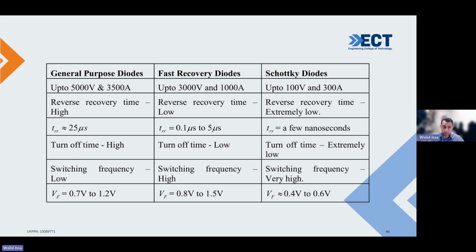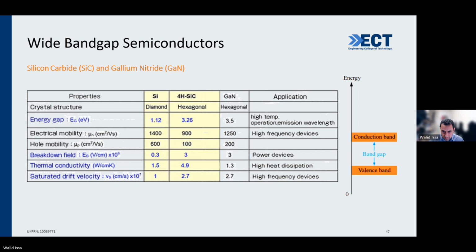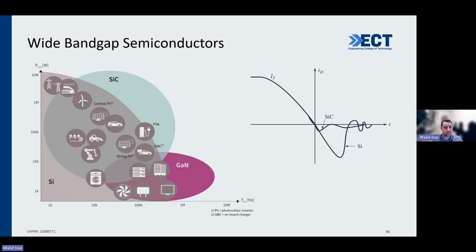And I'm now telling you about the questions to ask ChatGPT, for example. You ask them about what is the difference between silicon carbide and GaN, and why they are good for power electronics devices. For example, silicon carbide has thermal conductivity about 3 or 4 times more than silicon. What does that mean? When they dissipate heat, they don't trap the heat inside. They release it to the outside more easily than silicon. That means they can work in harsh environments, and the heat sink and fan requirement will be less. Okay, so that's the good thing about silicon carbide.